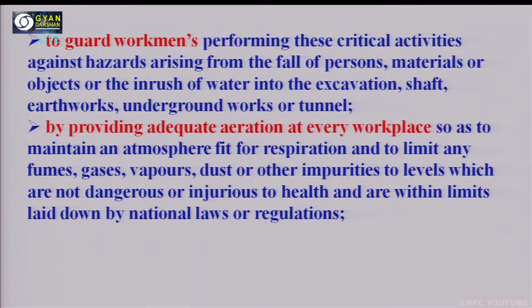Then, to guard workmen performing these critical activities against the hazard arising from the fall of persons, materials or objects, or inrush of water into the excavation, shaft, earthwork or groundwork or the tunnel, we have to make provisions to safeguard our workers. How can we do that? By providing, as I told you, shoring and sheeting that can avoid the falling of the material.